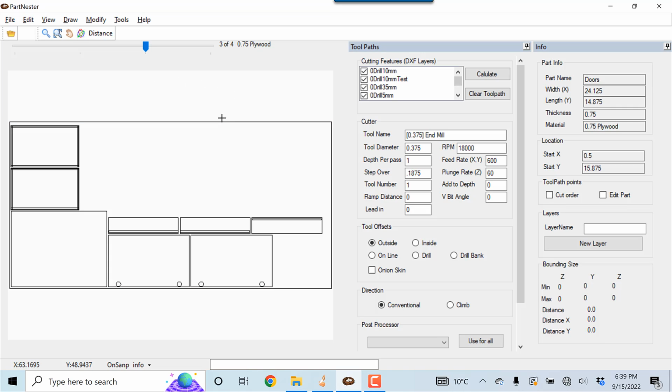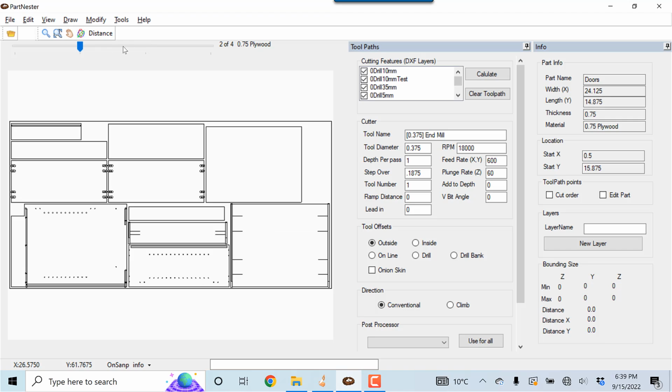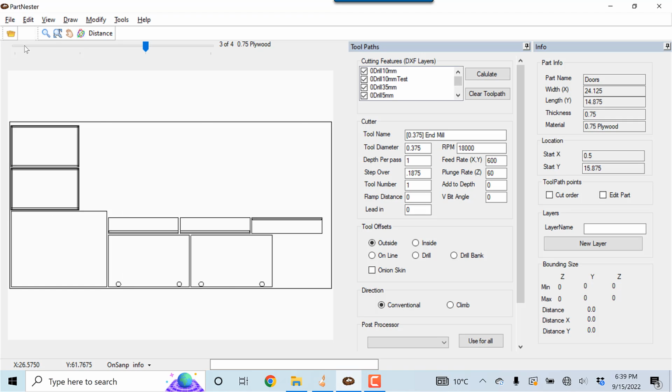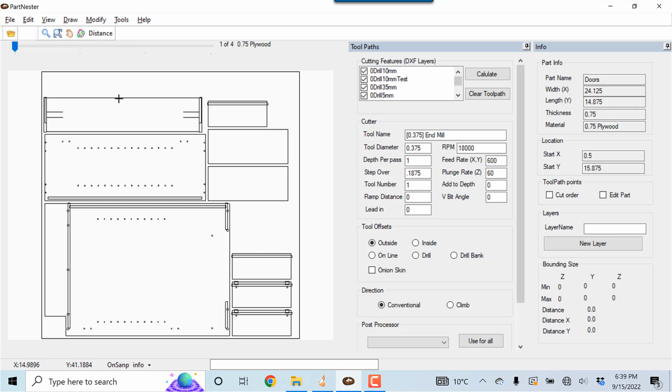This is one of the reasons, just a little tip, why I don't think it is worth saving and utilizing scrap, because it just created another piece of scrap that we used here rather than just using 2 pieces of 4x8. It's going to take a total of 3 sheets to cut this by utilizing that scrap, taking a little bit longer.